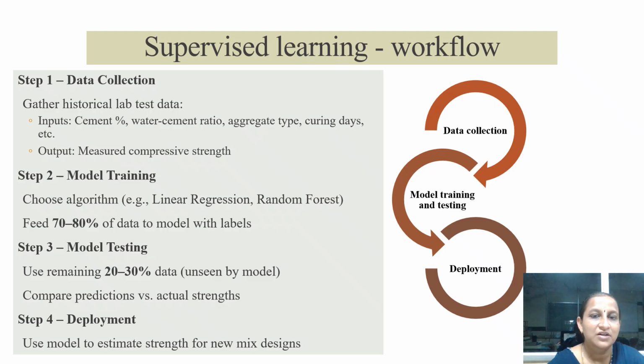Next we'll see the workflow of supervised learning. Here I've taken an example of predicting the compressive strength for a new concrete mix design. If you see, the first step is data collection, where the data will be collected. The required data are cement percentage, water cement ratio, aggregate type, curing days, and any other concrete ingredients used. The output required is the measured compressive strength of concrete.